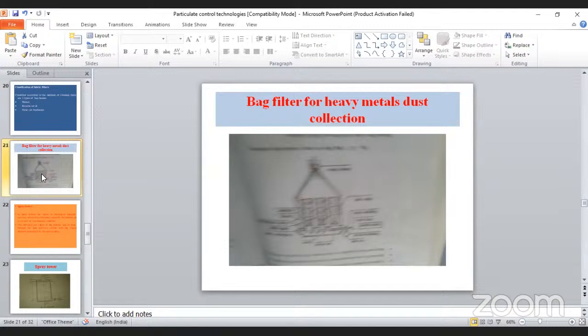Here the surface area occupation of the gas stream is very important. If we make only one filter and pass the gas through that, we cannot assume that everything can be filtered off at that time. So what they do is make the filters as small compartments, and all the compartments they put in one big container or device or hopper.